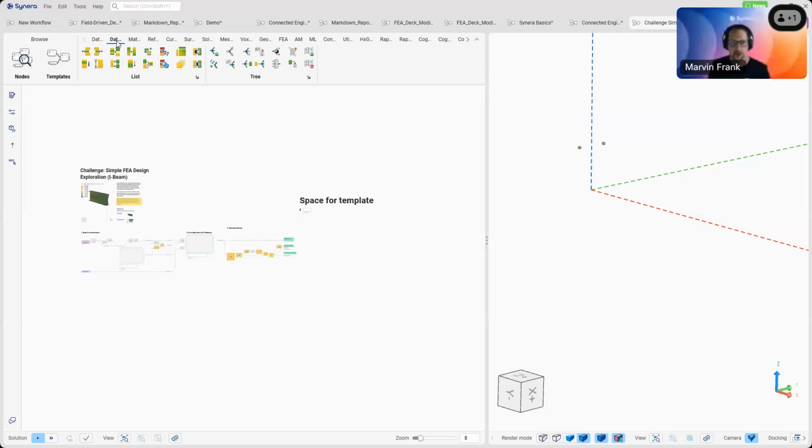For this, we can turn this stress distribution into a field. The fields are also available under the math section here, fields. So there are point fields, local fields, global fields. That's a whole topic in itself. I just want to quickly highlight what you can do. So you take the stress distribution, normalize it, and then turn that into a field.